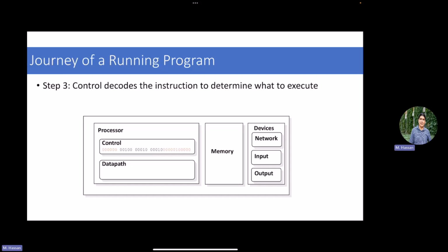So you have a sequence of zeros and ones. How do I know whether it's an add, subtract? What are the addresses of the registers? This is done through what we call a decode stage. So fetch, you obtain something from the memory to your registers through the control path of the processor. And decode means there is a decode unit. It's basically a bunch of decoders and gates that try to understand for this sequence of bits, what do we really mean? Are we adding R1, R2, R3? Are we multiplying two other registers with the result in R10? So all of this is being decoded through a circuitry that we usually call the instruction decoder, right? And in a pipeline, it's called the decode stage.